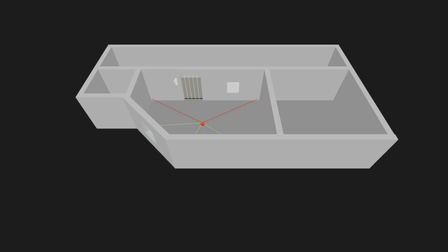So with vertical ray probing, we find voids from the floor mesh perimeter, and as you can see we've already placed, for example, a door sensor in the 3D environment, even though it's just scaled up a bit for demonstration purposes. The door sensor itself has been placed by a rule at about 80% of the height of the room. Even though there's no room here, the height can be inferred by vertical raycast. So it's 80% up on the room and a little bit to the left of the void at the door. And then the CO2 sensor on the right is placed on the largest wall segment at the interior wall.